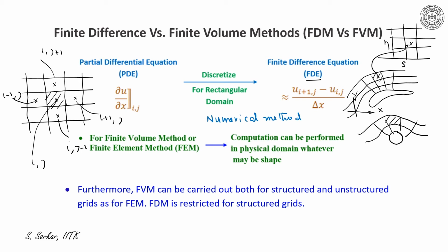The differential equation will be transformed from the physical domain to the computational domain, thereby the governing equation now would be very complex, having some extra terms, and then we discretize this transformed partial differential equation and solve by some numerical techniques.